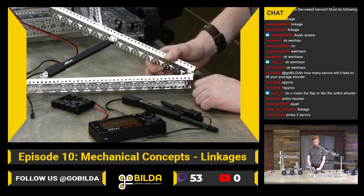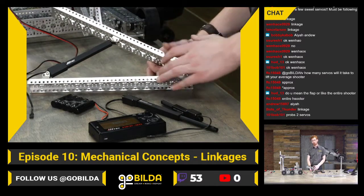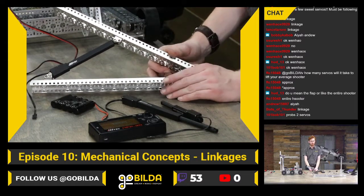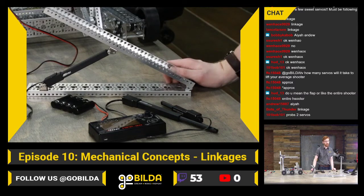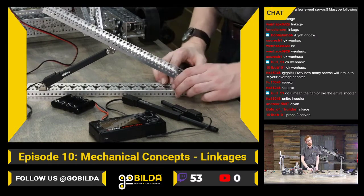Now in that case, you could put a 1 pound servo 6 inches from the pivot point, or you could put a 6 pound servo 1 inch from the pivot point, and require that servo to move a lot less. So it all kind of depends on exactly what your use case is.